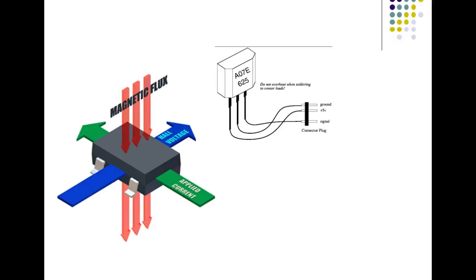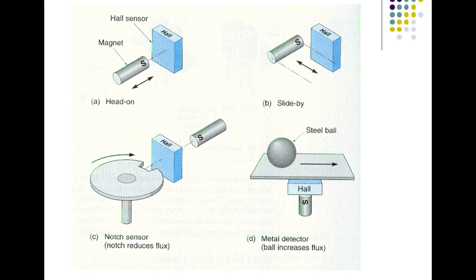So a Hall effect sensor, we can make it sense metal by putting a Hall effect sensor between a permanent magnet and the metal we're trying to sense. Because magnetic field automatically concentrates to metals, right? You understand that? So these are different variations.